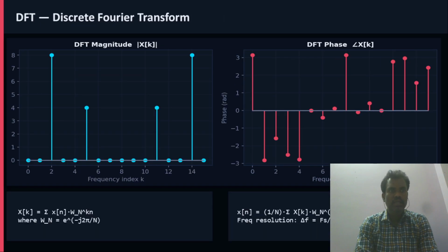That is the new transform obtained by applying sampling in the frequency domain. That is called the Discrete Fourier Transform, because here the term discrete is used for both time as well as frequency. Both become discrete. But previously, in the discrete time Fourier transform, only the time domain was discrete, but not the frequency domain.